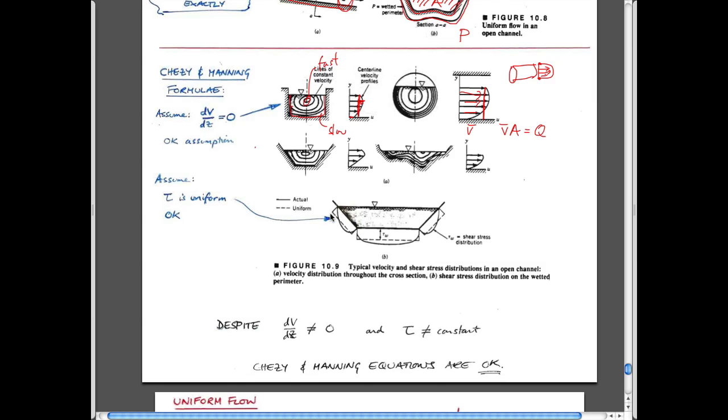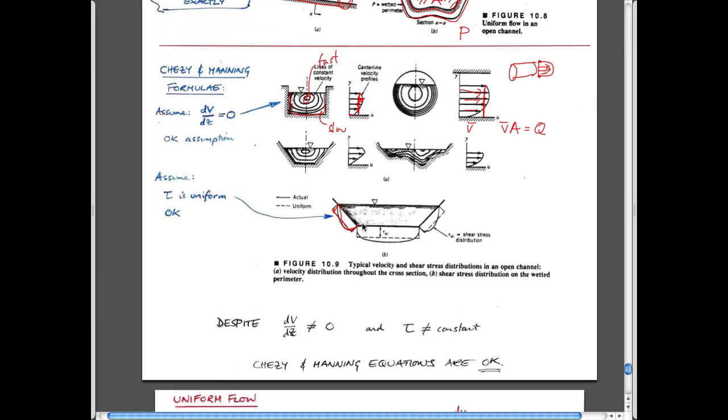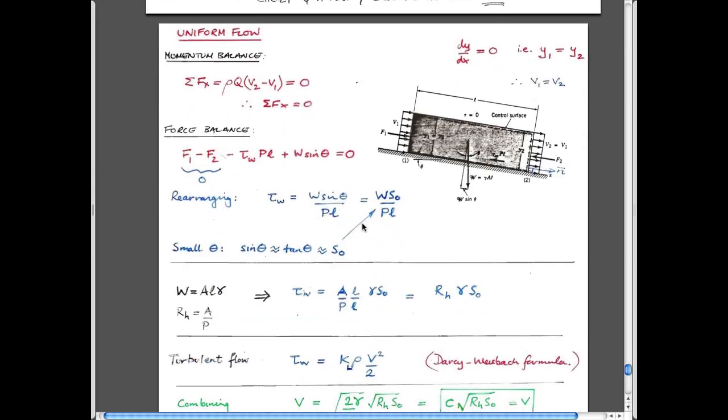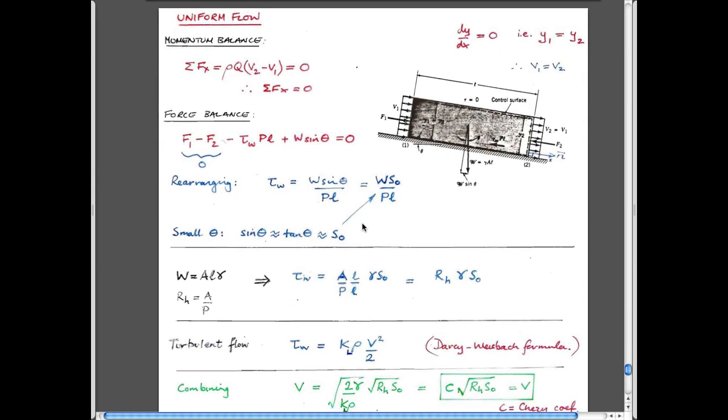We'd also make some assumptions that the shear stress that's retarding flow, same as the shear force that's applied on this bag by friction dragging across the table, water flowing past the banks will have the same thing. Maybe if it's going at zero velocity at the top and going at a higher velocity here, then you'd expect that the shear stress that's applied into the page might vary like this, but actually we're going to just assume that it's uniform along the side, which is really what we did on pipe flows as well. Okay. So that's the basic precepts of what we'll deal with.